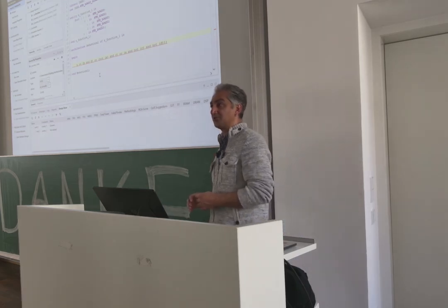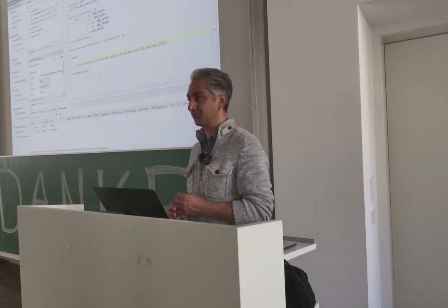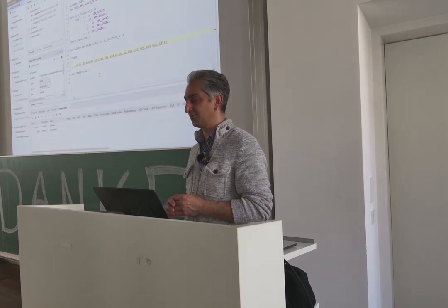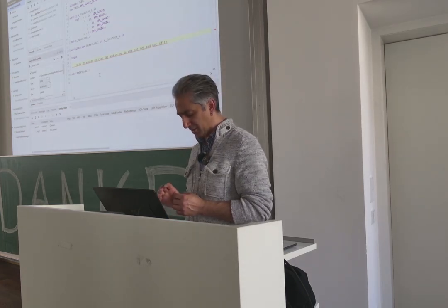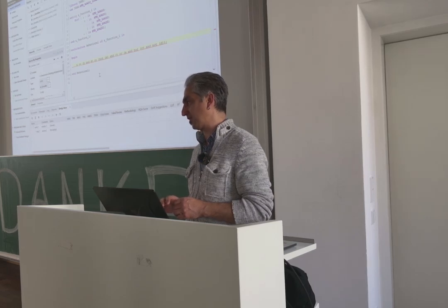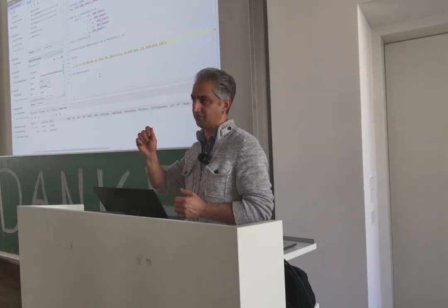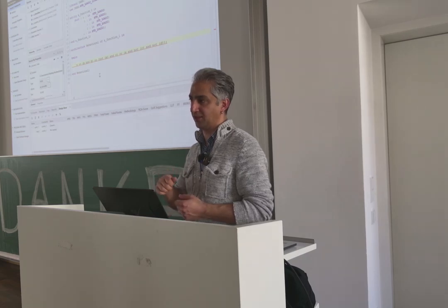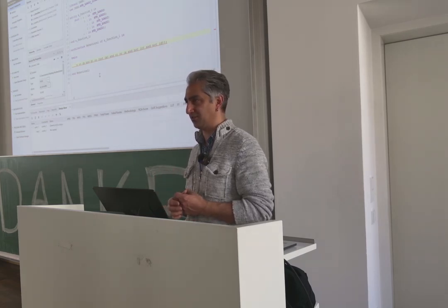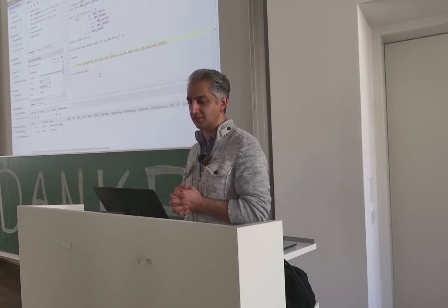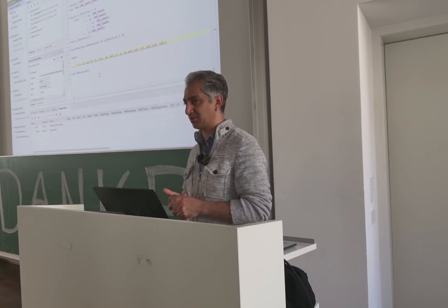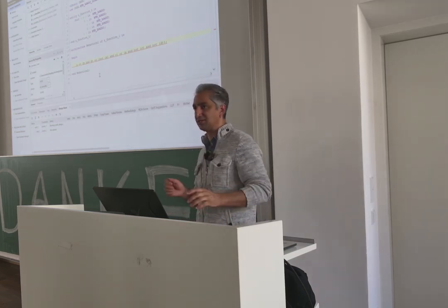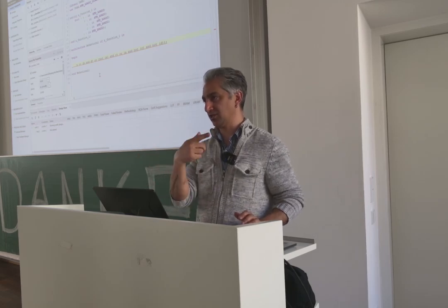During this time, any questions? The in-out option, is it for debugging, or what is the purpose? There are some modules that you can define in hardware as in and out by some selection bits, for example open collector signals. Probably you're not aware of this, because it's too much electronics. You can do it, but usually in simulation, in-out works easily, but in reality, in FPGA and also in ASIC, this needs another control signal to say which direction you have.